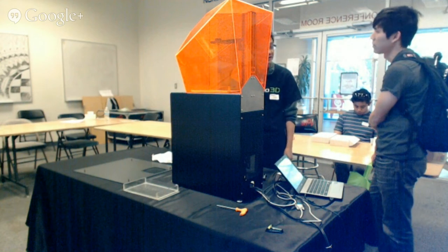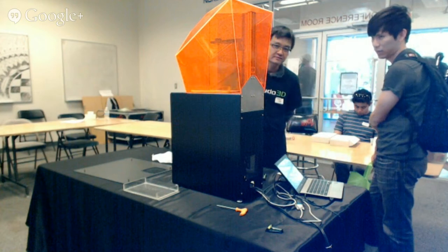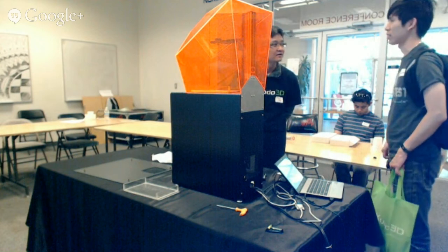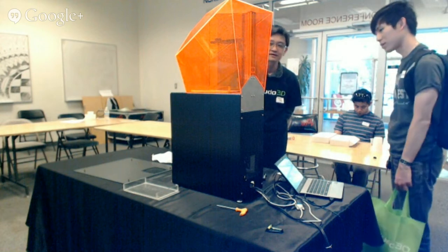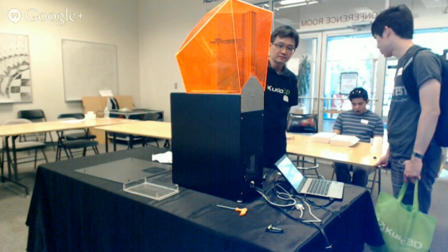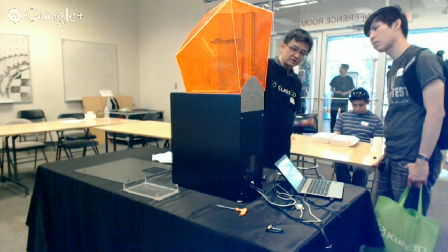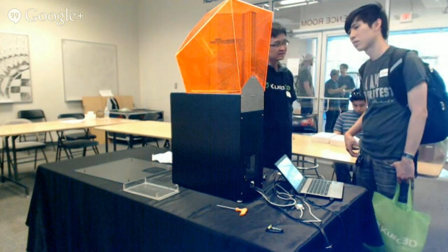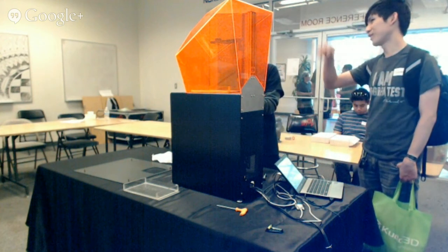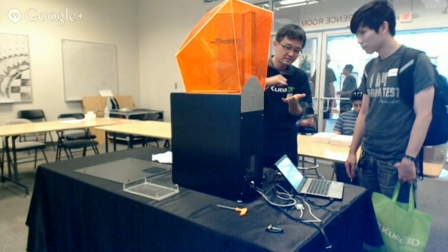Most tools, like Creation Workshop, the slicer that Ted was showing, have built-in printer control. But that only has 2 settings: there's only attachment and then the rest of the part. Most printers only need 2 zones, one to attach to the build plate and one for the rest of the part. Most of these other printers don't need the variation that we do here because of the flexing, especially the non-linear flexing effect.